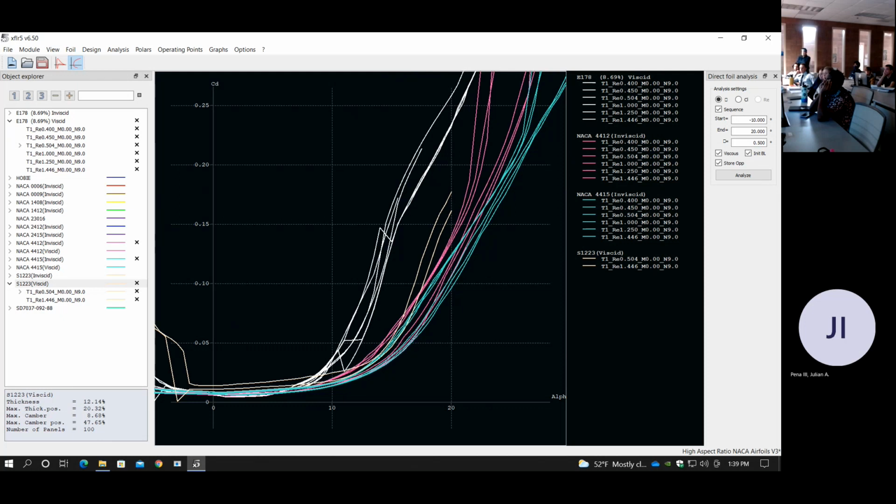In the 3D wings, I was able to get my 3D CL and CD values and induced drag, and from that I was able to calculate the sink speed, and basically the time it takes for it to glide to the ground.